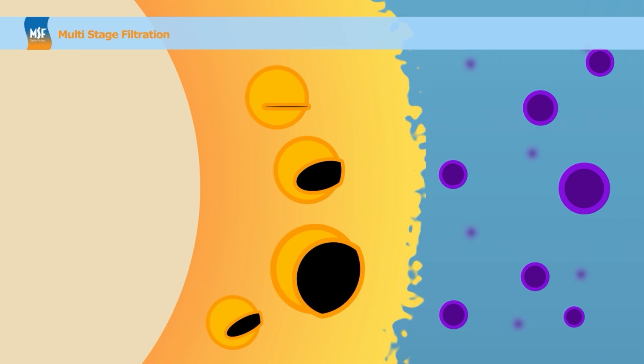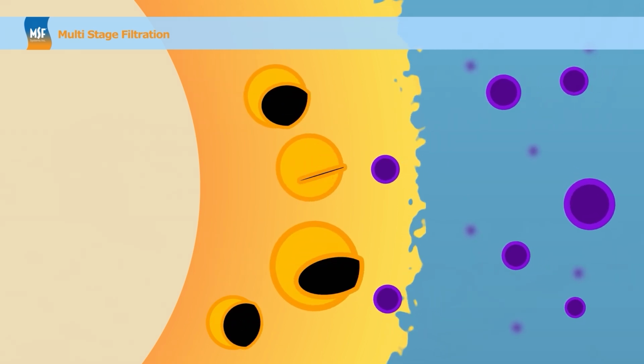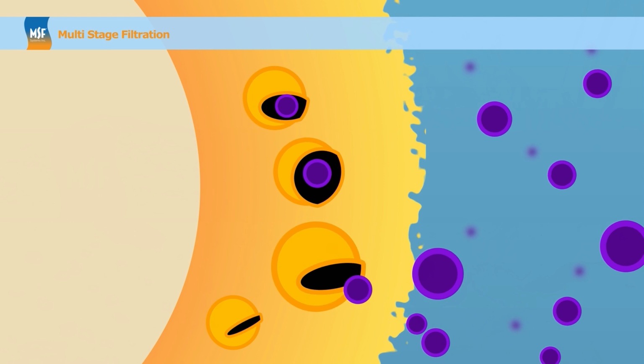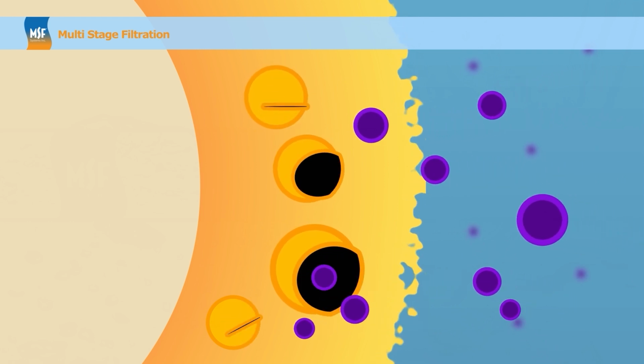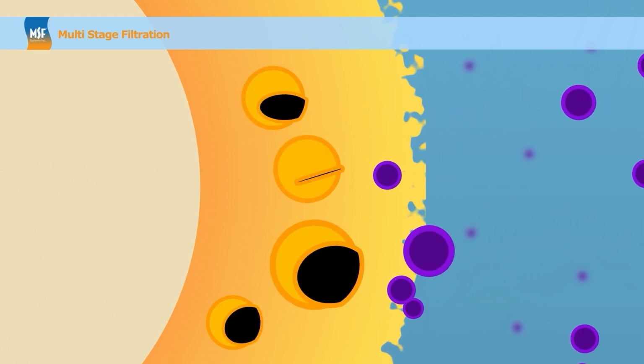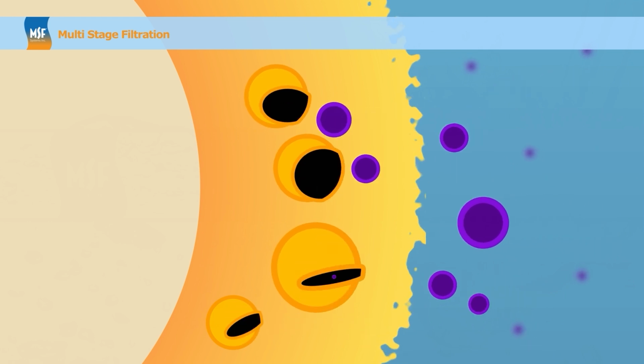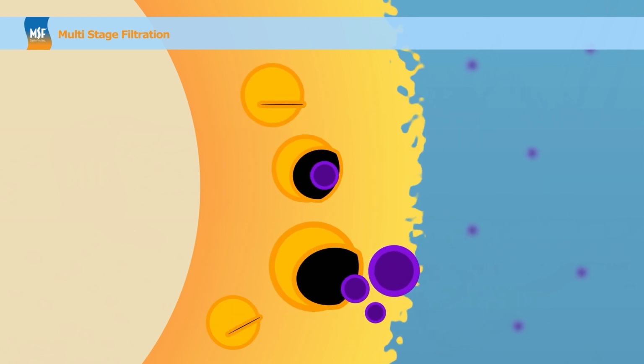The organic predation process consists of larger organisms preying upon and digesting smaller organisms, further filtering the water while feeding and maintaining the health of the biological layer. That polymer coating containing predatory organisms is called the Schmutzdeck, and it is the life of the slow sand filter.